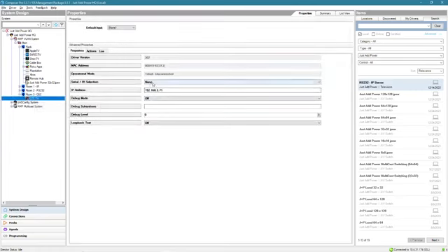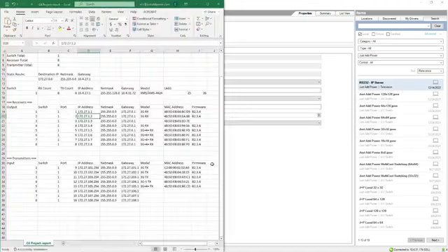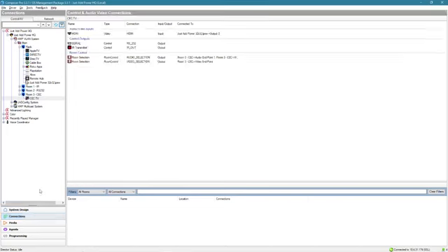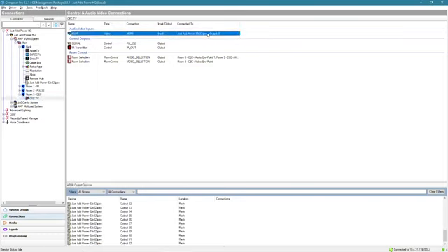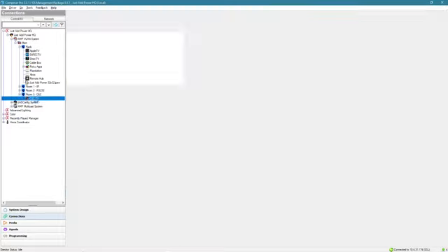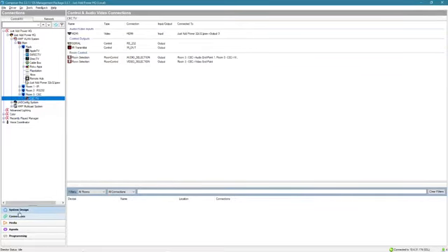Once we've done that, we leave our serial IR selection to none because we're not using serial or IR, and we do the same thing we did with the others. We go to our project file, we find the receiver that's for that room, copy that IP address, set it in, and set. Now, we don't have to make any connections because we've already made that Just Add Power driver the endpoint for the HDMI in that room. So if we look at that room, that CEC TV, we'll just rename this so that it's clear.